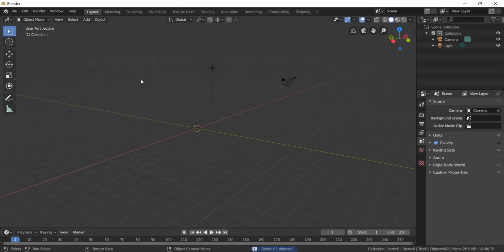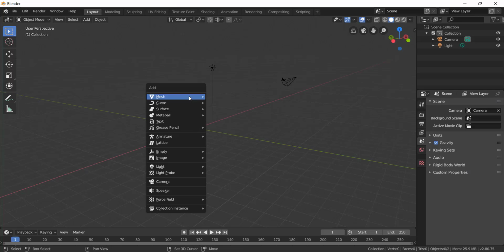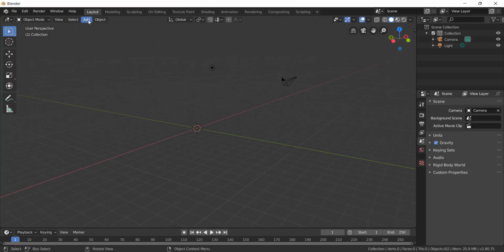The other thing is there is always a shortcut for everything in Blender. We always use shortcuts, so I will tell you the shortcuts. I will not concentrate on these things, I will just make you focus on the shortcuts. Just keep track of the shortcuts I'm saying. Shift A, Shift plus A, you should click both at the same time. Shift A will open the same Add. If you hover on that, you can see the shortcut Shift A, right?